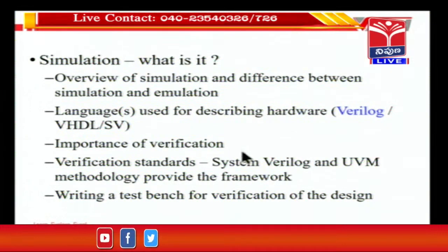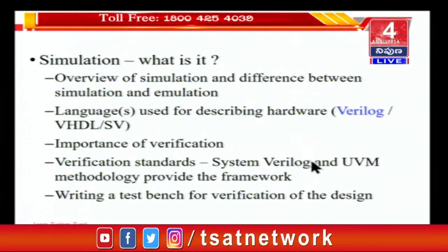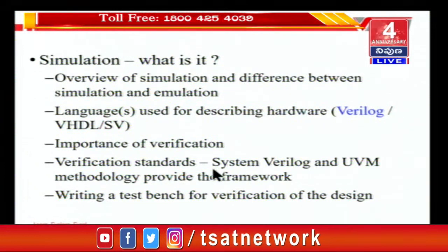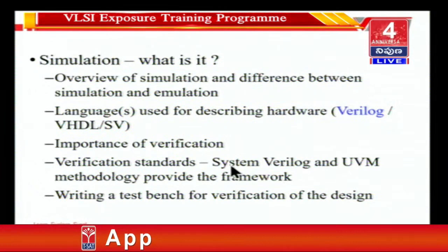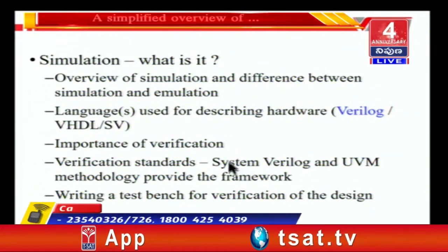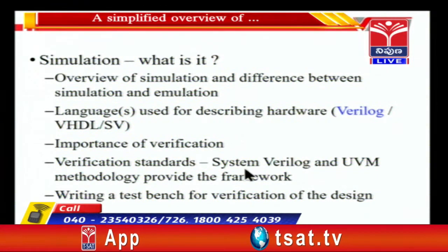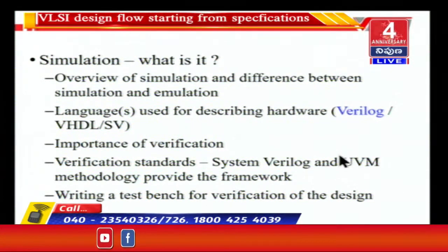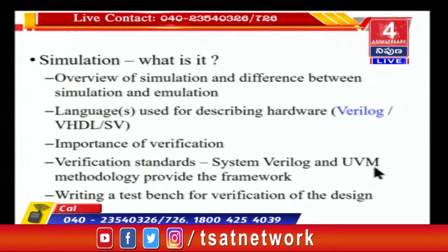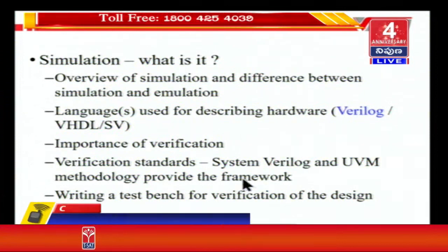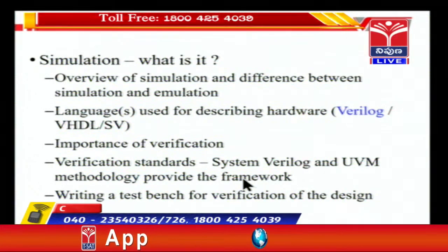Almost all standard verification test benches, when I say test benches, it means verification test benches, are written today using System Verilog. System Verilog is the language of this test bench, and UVM, Universal Verification Methodology, is the standard methodology that provides the framework for the verification test bench.